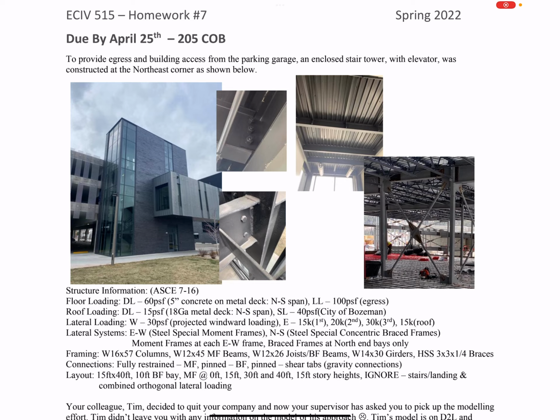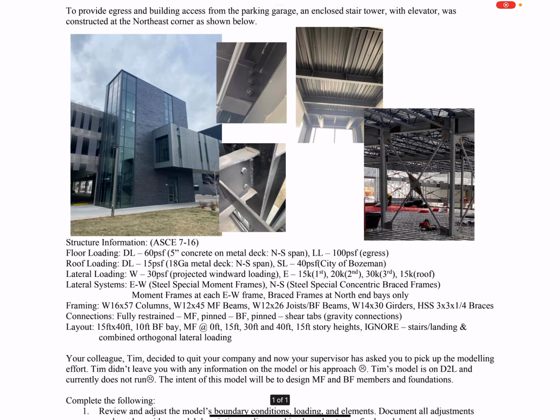I gave you structure information, right? Floor loading, dead load, 60 pounds per square foot. This is a 5-inch concrete on metal deck. It spans north-south. The live load is 100 pounds per square foot because it's egress, right? You get that out of ASCE 7.